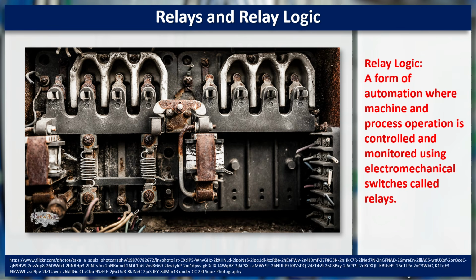Thanks, Alan. I'm Nancy, and I will be assisting Alan through the series. Now, let's look at electrical relays. Relays are electromechanical devices that act as controllable switches. When a number of them are used to control machinery, we call their sequential operation relay logic. Relay logic is defined as a form of automation where machine and process operation is controlled and monitored using electromechanical